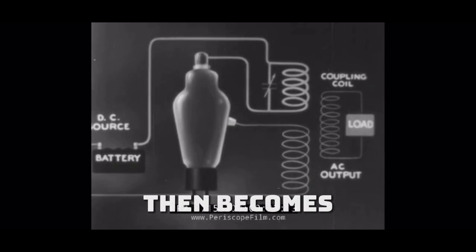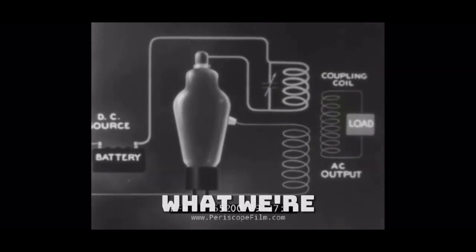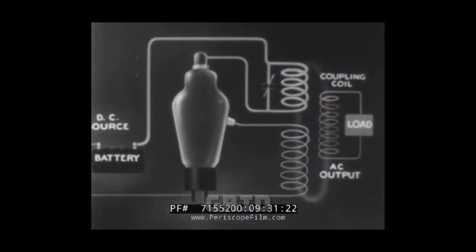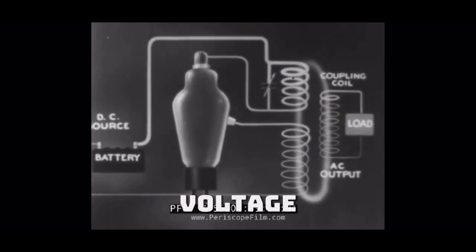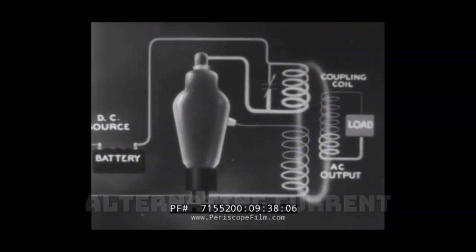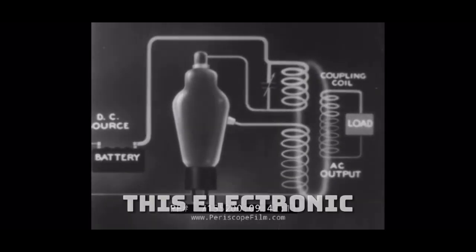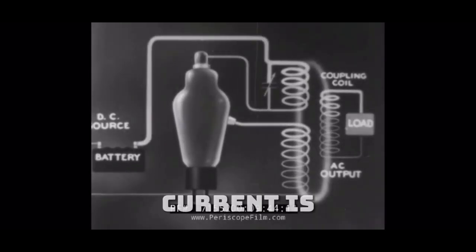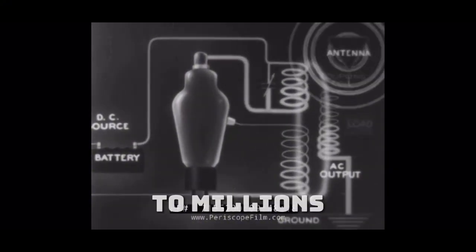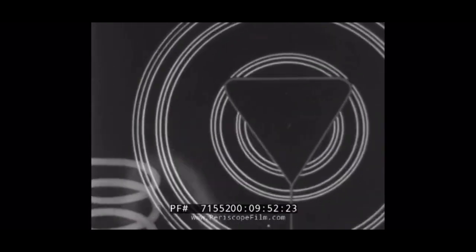The system then becomes capable of changing direct current into alternating current. Note that what we're doing in this case is amplifying in the usual way and then feeding back to the grid part of the amplified voltage. Continued repetition of this feedback results cumulatively in a strong alternating current. This electronic means of generating alternating current is important because it can produce very high frequencies up to millions of cycles, far beyond the range of ordinary rotating equipment.